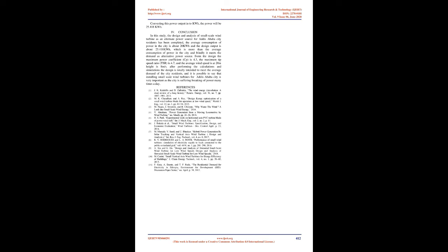Twist angle versus radius. Care should be taken in designing twist angle because the power production and safety of the wind turbine depends on it. This design has a maximum twist angle of 25°, Figure 5. As the radius of the blade increases, twist angle decreases in a different pattern as shown in the graph below. And this permits the blade to harness wind effectively. Fig. 5. Radius versus twist angle.